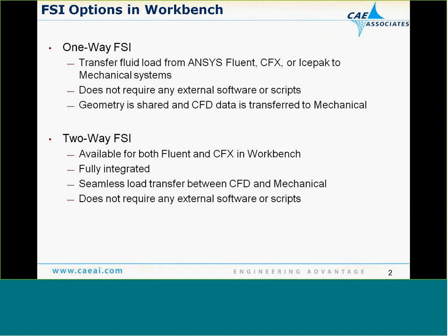We're looking at the one-way FSI, which means you can transfer fluid load either from ANSYS Fluent, CFX, or Icepak to Mechanical systems. This does not require any external software or scripts to couple these elements in Workbench. And geometry is shared between CFD and the Mechanical systems, so it's really convenient. There are a couple of reasons we want to do this, and we'll see as the presentation goes along why we want to transfer the fluid load into the Mechanical system.